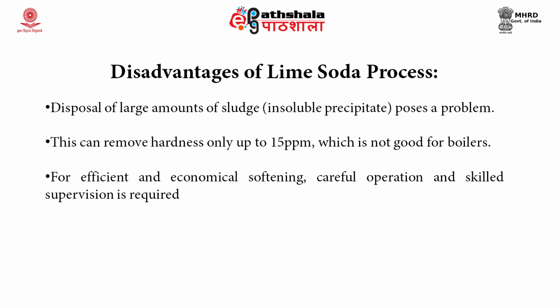But the disadvantage of this lime soda process is that the disposal of the large amount of sludge which is formed is a problem, and this process can remove the hardness only up to 15 mg per liter, which is not good for boilers. For efficient and economical softening, careful operation and skilled supervision are required in the lime soda process.